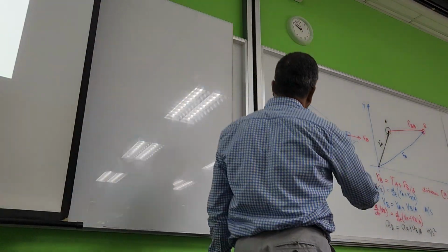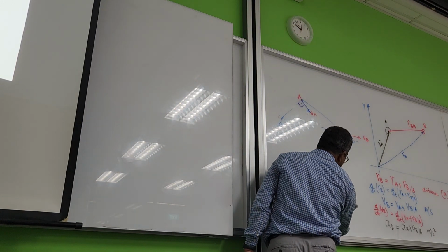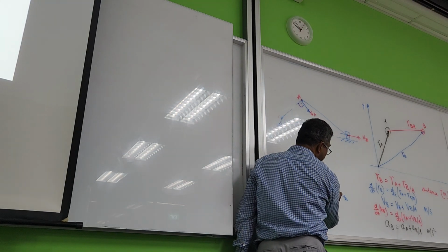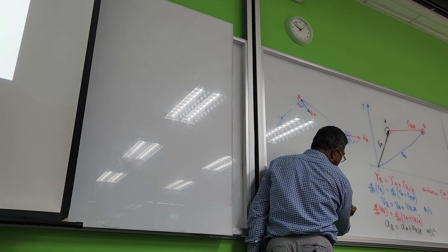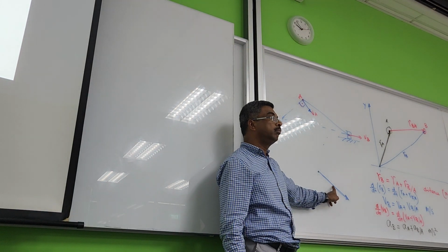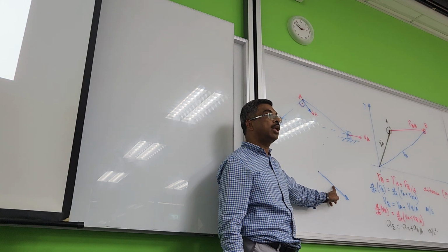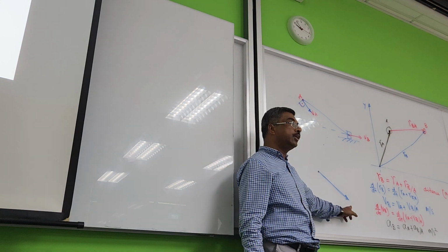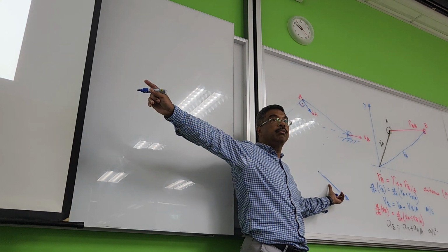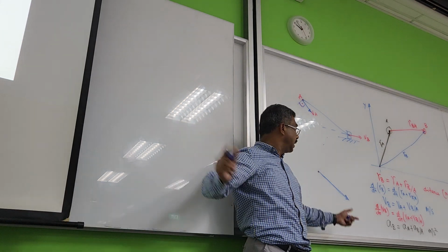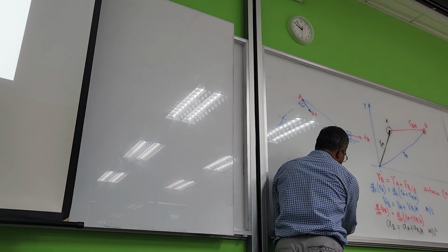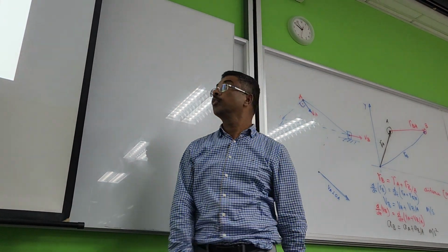So I bring it here. And how many millimeters is it? 10 millimeters. So say it's 10 millimeters here. Look at here how I did it. That is the length of 10 millimeters. Where it finishes, I finish with an arrow. Do not put the arrow in the middle. Because if you put it in the middle, it shows direction. It doesn't show the magnitude. But here, this arrow shows the direction and the full scale of 10 millimeters per second. Follow the grammar. And now, I nicely write VA perpendicular to OA. What are the things I have written there?